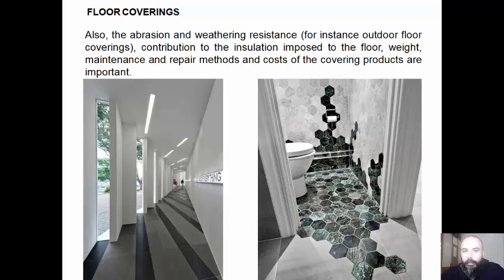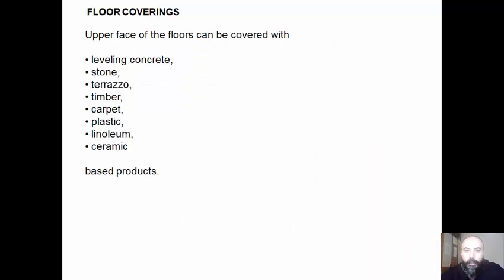Also, the abrasion and weathering resistance, for instance, outdoor floor coverings, contribution to the installation imposed to the floor, weight, maintenance and repair methods, and costs of covering products are important. Upper face of the floors can be covered with leveling concrete, stone, terrazzo, timber, carpet, plastic, linoleum, ceramic-based products.